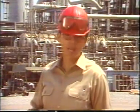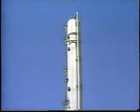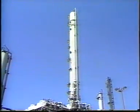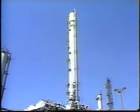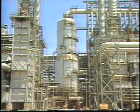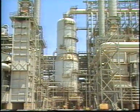In any refinery or chemical plant, you'll find that distillation columns are designed differently to produce different kinds of products. The column shown here separates two products that have a very small difference in their respective boiling points. This is a difficult separation that requires a large number of trays, so the tower is very tall. This column is much shorter because the products it separates have relatively large boiling point differences and fewer trays are needed to make this type of separation.